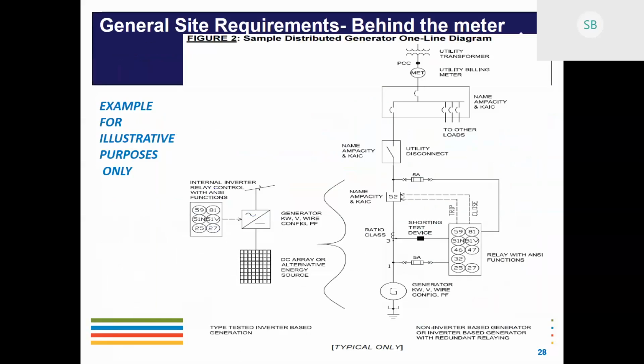That's the IPP. This next one here is what we call behind the meter. And again, for those that don't know that term too well, it's anything like a commercial or industrial complex that has load associated with it, and you're just adding the generation into that facility. So at your metering point, there would be a load element and there would be the DG element. So some slightly different requirements as you go through those types of setups. But this is basically showing you still have the same major components. You're still going to have a utility disconnecting means. There'll still be a recloser or breaker in between the DG and our system. So the requirements and the intent is still more or less the same, but the analysis is just a little bit different.